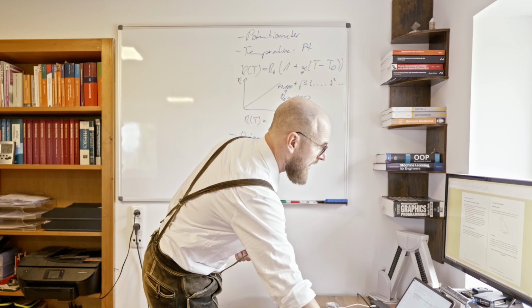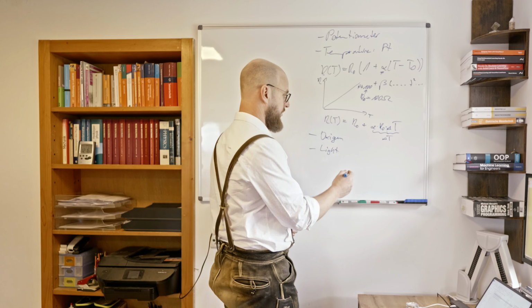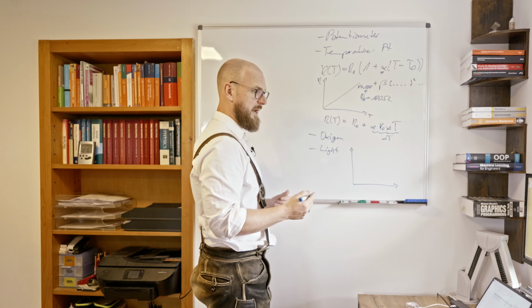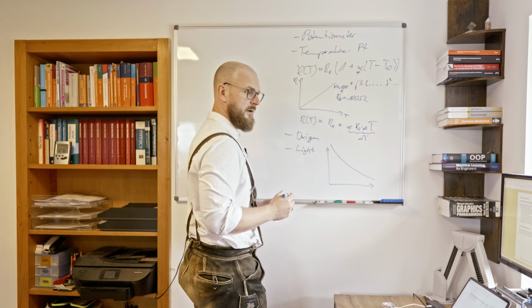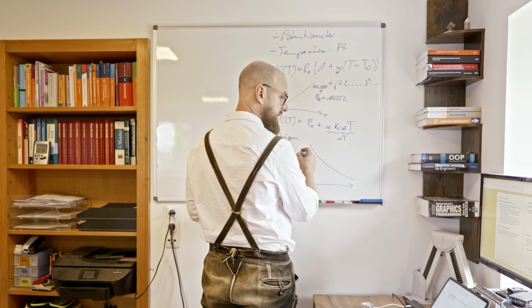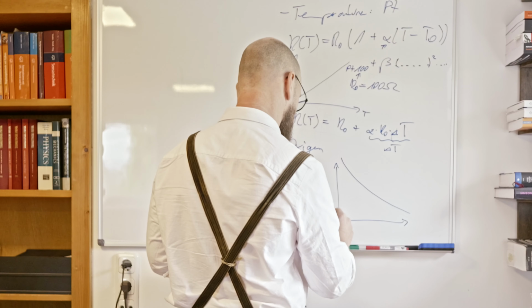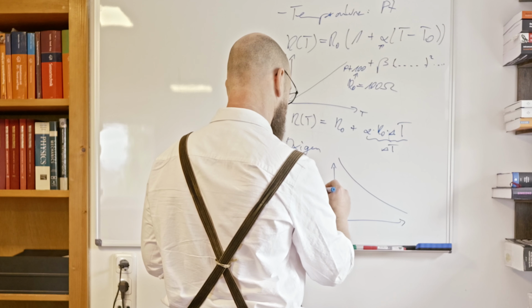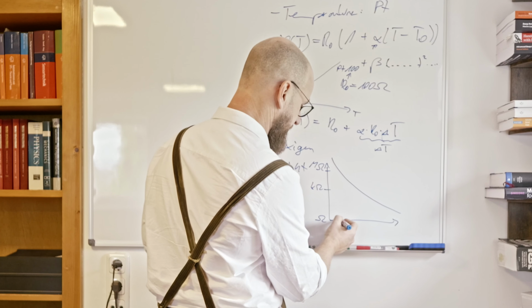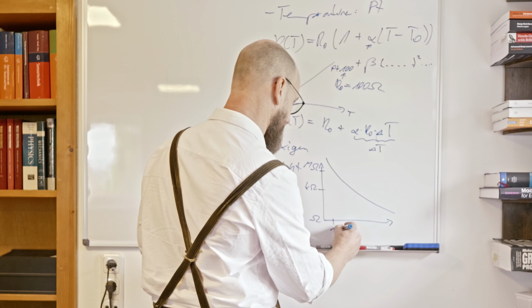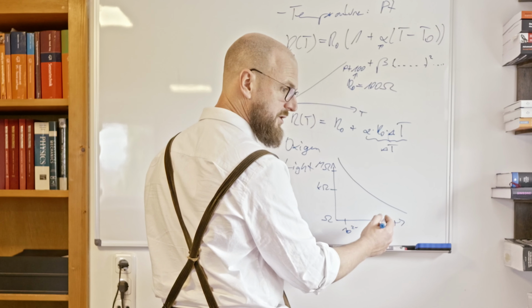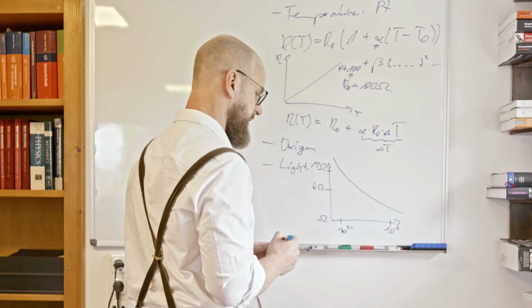Moreover, there are examples of measuring light intensities, meaning we have some photoresistors which have a very strong dependency on the reaction to light, changing their resistance, meaning we have somewhat ohm range over here, kilo ohm range over here, and mega ohm range over here, at the very steep places, correlating to a light change of 10 to the minus 2 to a light change of 10 to the 4.